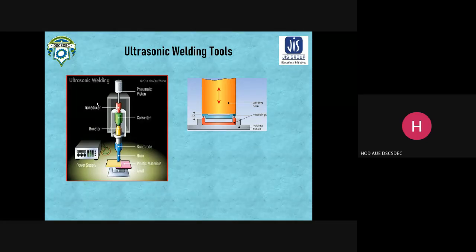are the two main parameters of ultrasonic welding. So we are now discussing the pressure which is to be maintained. This machine has a pressure gauge and a regulator for adjusting the welding force which is required. Obviously, in case of plastics, the welding force required will be less. But when we are concerned with welding of metals, then the welding force may be increased. That means high pressure can be required.